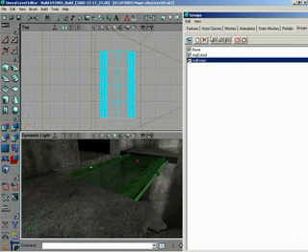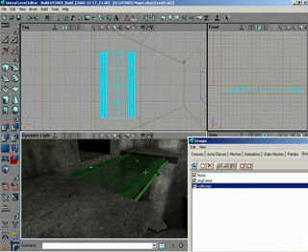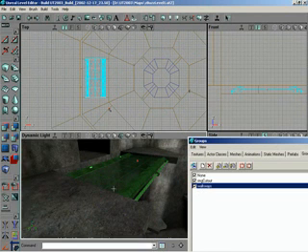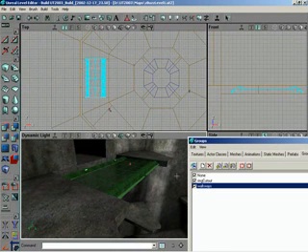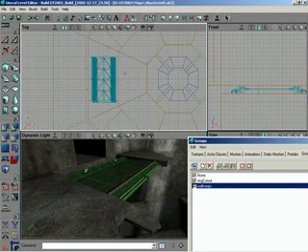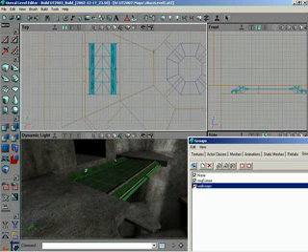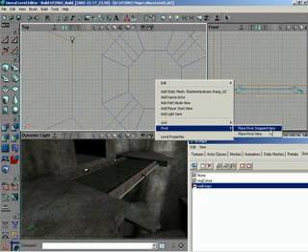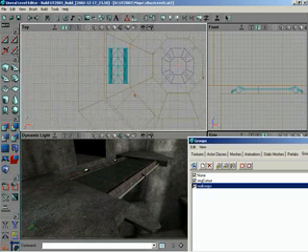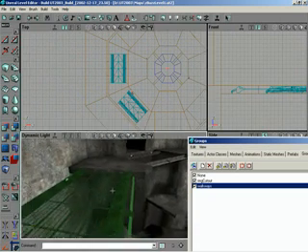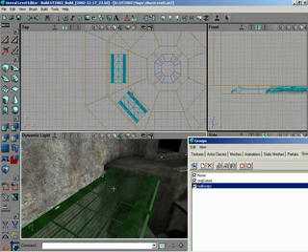Now, let me move this out of the way a little bit. When we go to start duplicating these, we can quickly do the same thing as we did when we duplicated the brushes all the way around, we can keep reselecting them from the group browser. So with those 2 selected, I'll hit Control W to duplicate them, drag them back to the center, and then set their pivot to the center of the world. Pivot, place pivot, snapped here. And then I can Control right drag to rotate them. So now I've got 4 of them, spanning 2 of the walkways.